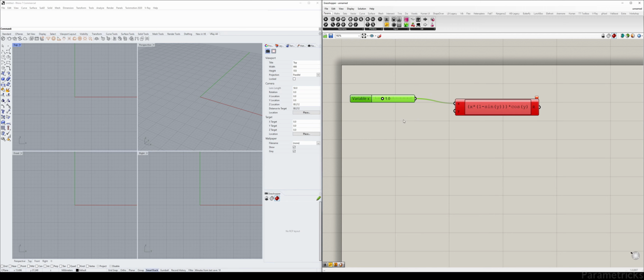And then for the y value, this is going to be a little bit trickier. This is also a value that I found through trial and error. For this, I will create a panel, a panel that just quickly makes a domain 1 to 3. So this is going to be a domain, and we're going to make a range, actually, because we want to have a few numbers. We're going to have a few numbers between the domain 1 to 3 and the amount of numbers we want. Let's start with 10, because this doesn't really matter as much as you will see later on.